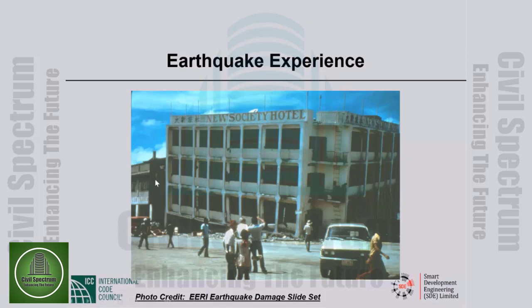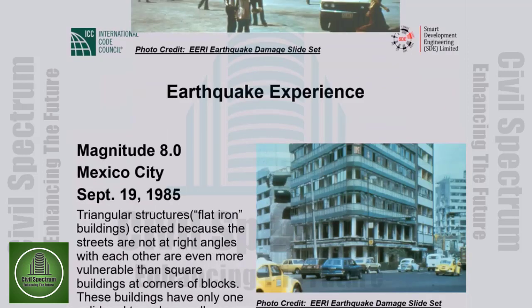So typically, you would have shear walls on the left face of this kind of building and on the back face, but on the street facing faces, there would be no shear walls, for obvious reasons. And that means significant torsion. And because of the torsion, the ground story has failed. The building, at least in these parts, is one story shorter than it was before the earthquake. So torsional irregularity is a problem.